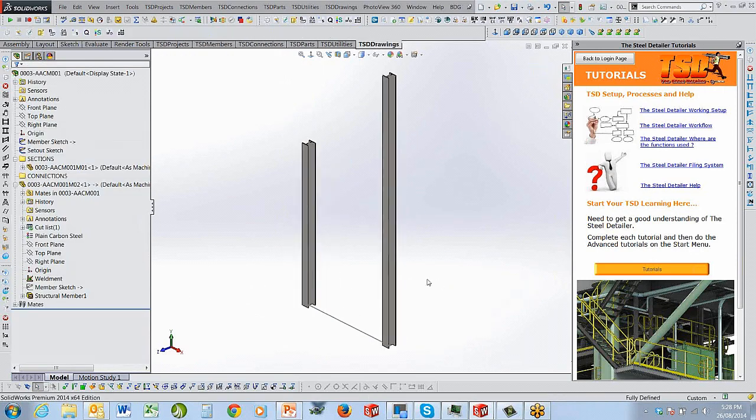Okay. So you can see how my driving sketch is now attached to the whole process. Now I've got my driving sketch here and I've got my member sketch driving my driving sketch. That's what we do with welded members. So if you wanted to do a frame of some sort, just create a set out sketch and your member sketch is there. Now you can set it up so that the bottom line is also a second member sketch so that you have 2 items to select. I'll show you that in a second so that you can see how all that works as well.